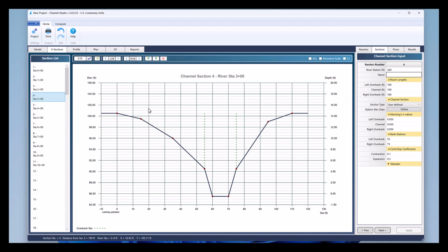So you would go ahead and enter it in as if you're looking downstream, and then hit this little rotate button right here, and it rotates the section. I'll do it again. Here's the original, and then here's after it's been rotated. And that's all you need to do. And so I'm going to go ahead and keep that rotated for now. I'll show you why later. It also goes up by 0.25 feet in slope, so I'm going to just apply that elevation adjustment and hit apply.